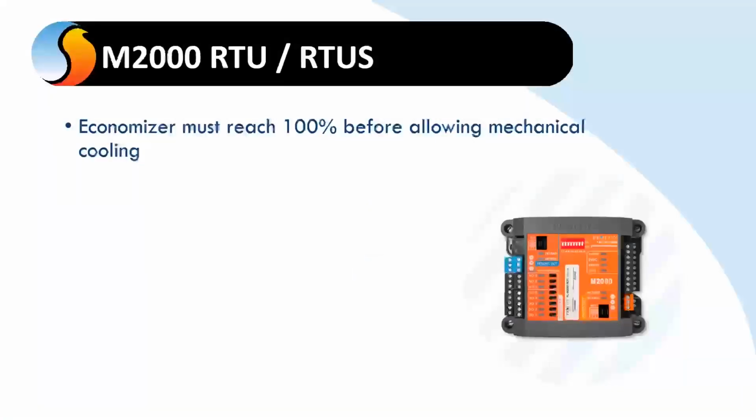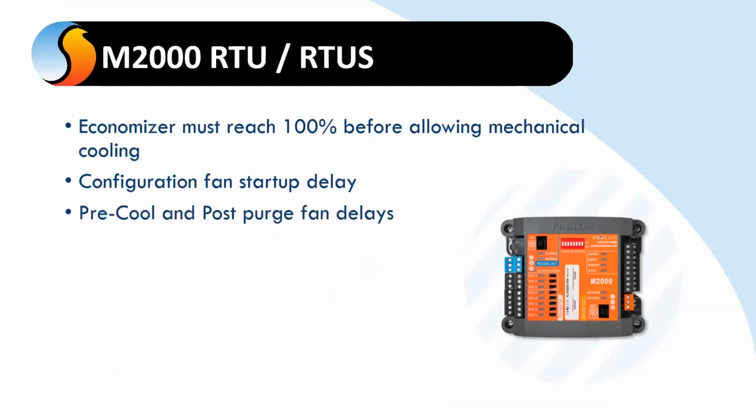Okay, so back over here with our PowerPoint. Again, we have the fan startup delay on the RTUs as well. That's what we're pointing out here. Still have the same pre-cool and post-purge fan delays with those as well.